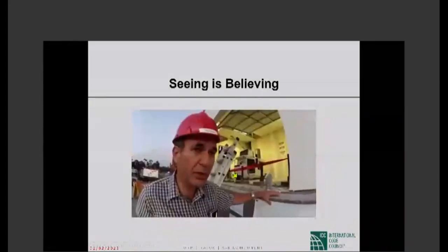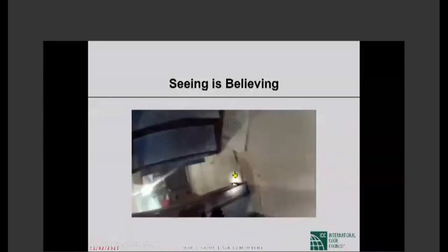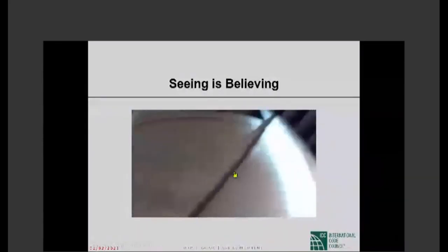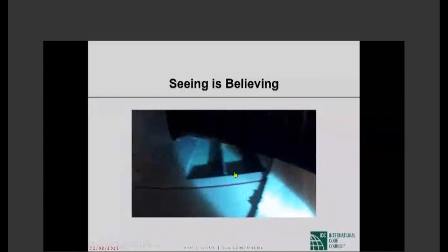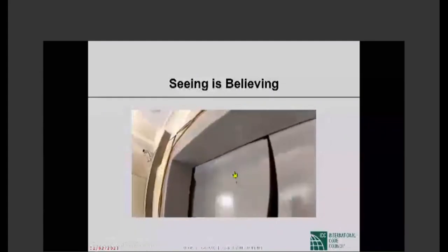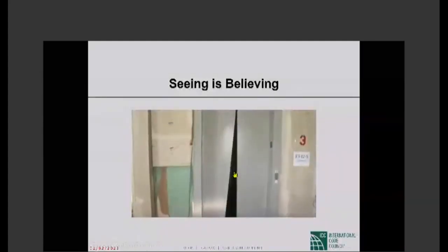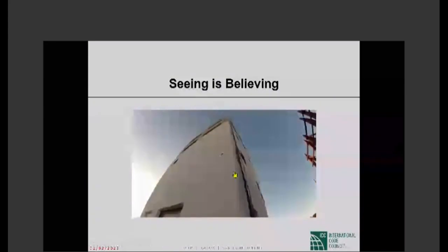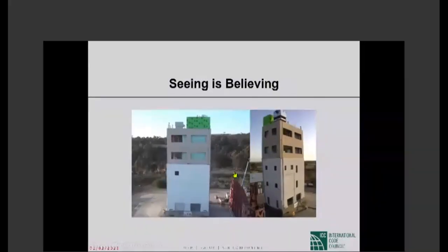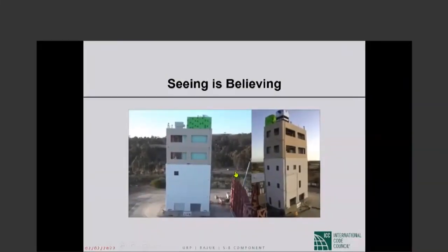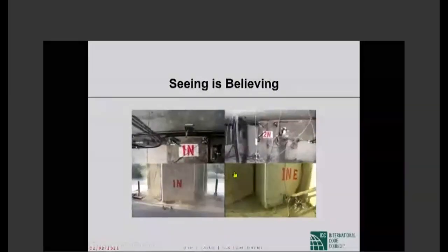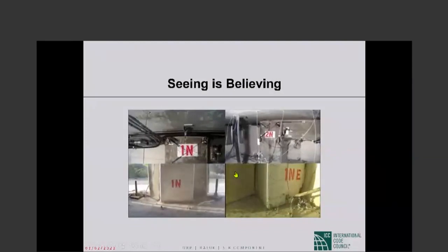From the third floor to the fourth floor, the stairs are detached. They are hanging. There is a lot of gypsum board, huge gypsum board that detached, that fell off. At every floor, the frame of the elevator door has been seriously damaged. The doors are locked in an oblique fashion. But the building has done its duty. It bent and cracked, but did not collapse. It satisfied the design objective. The structural system should still stand, even though maybe close to collapse, but still stand.